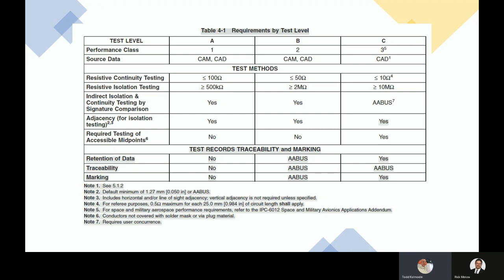So the difference there is our voltage. We didn't get into voltage really earlier on in this, but for most printed wiring boards to be acceptable by the military, for one, it needs to be a 40 volt minimum test. And there'll be a statement sometimes in a procurement document, or usually in a fab drawing, that says the rated voltage of this board is X. Sometimes it'll be 10 volts, 12 volts, 18 volts.